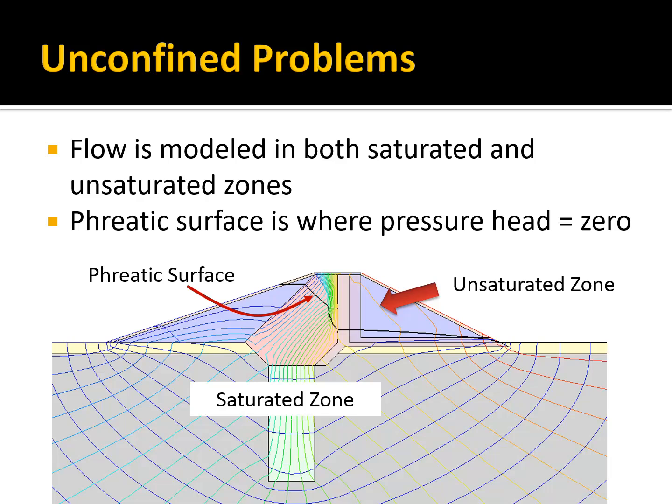What do I mean by negative pore pressure? And why do we even have water above the phreatic surface? Well, you have water that's pulled up into the vadose zone, we call it, the unsaturated zone, through capillary rise. And so in reality, you could have a small zone which is fully saturated but has negative pore pressures due to that capillary rise pulling the water up.